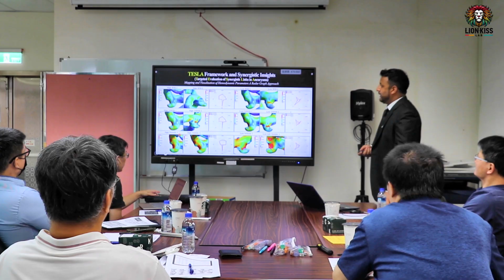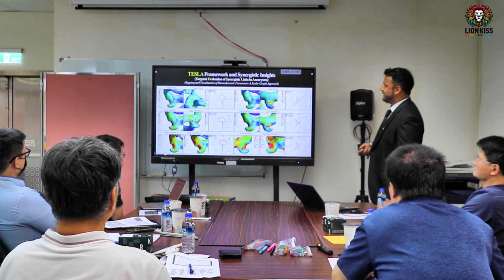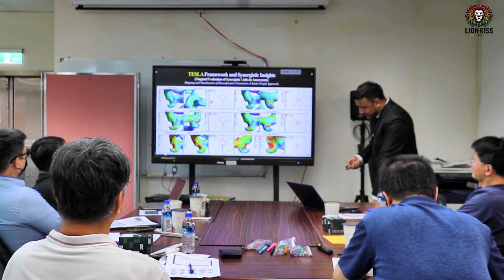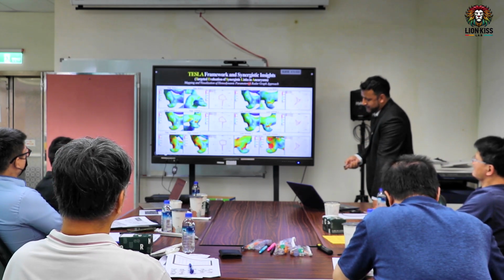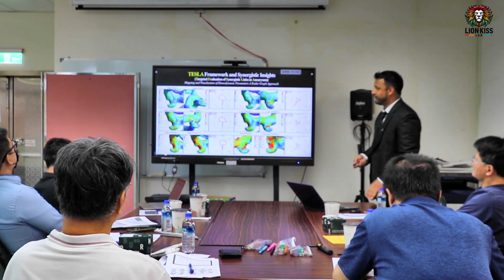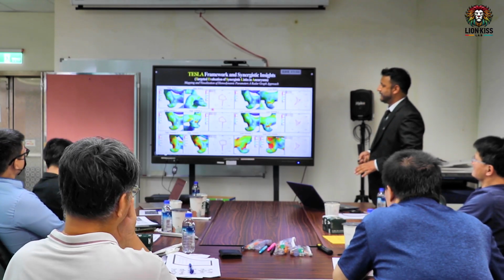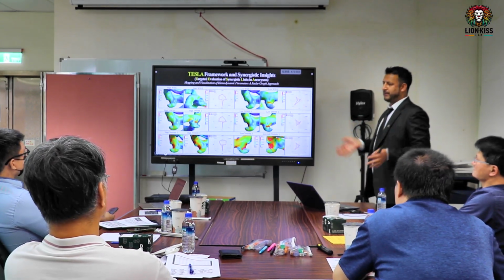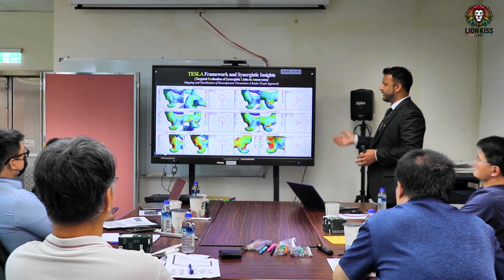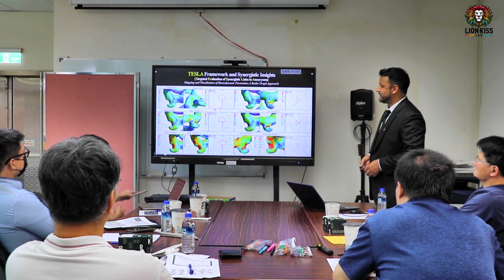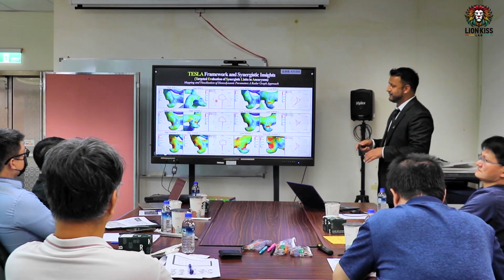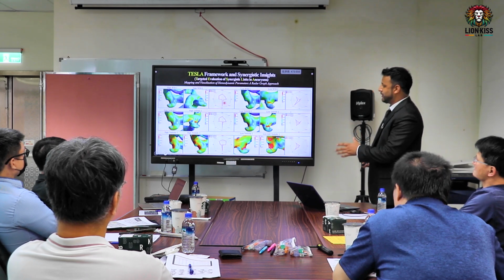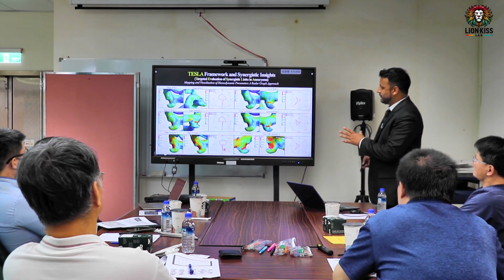So this one is TESLA. Why do we call this the TESLA framework in synergetics? It's a Targeted Evaluation of Synergistic Link in Aneurysm. When I find high wall shear stress at a location, I try to find other parameters like pressure gradient, velocity, and vorticity at that location, and we get a Tesla-shaped image. We gave this name because in all cases, when we see the high wall shear stress and measure the other parameters like TOSS with vorticity, it's Tesla.